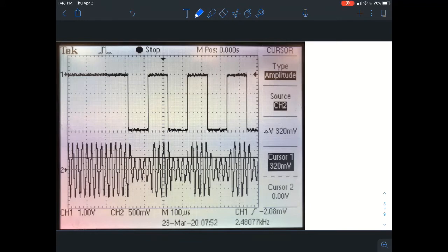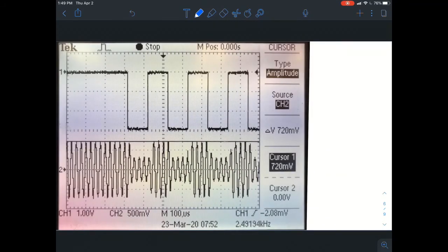Okay, so it also gives us some more information. For example, our high pulses are zeros and our low pulses are ones. That means in this waveform, this is a 1 and this is a 0. So one of the things they're asking us to do is measure what the voltage for a 1 pulse is. Sorry, pulse for a 1 bit. So this is going to be V sub C for a 1 bit. The next one we're going to talk about is the voltage for a 0 bit, and we have that marked out here, annotated there. So this is V sub C for a 0 bit.